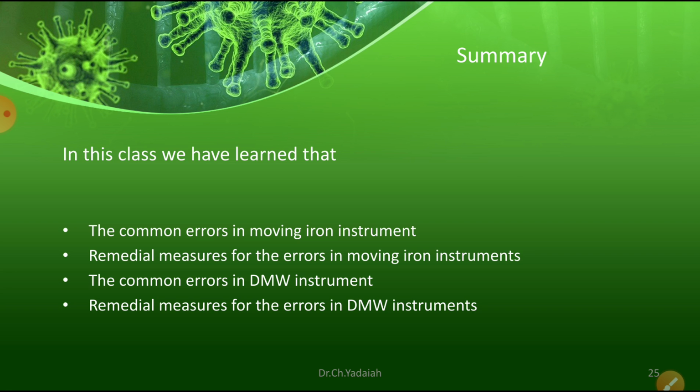Mechanical unbalance may take place if you are using more metal moving parts in instruments. So the remedy is not to subject them to any jerks during operation, keep the spindle vertical, and keep the instrument away from heating areas where you are going to measure.